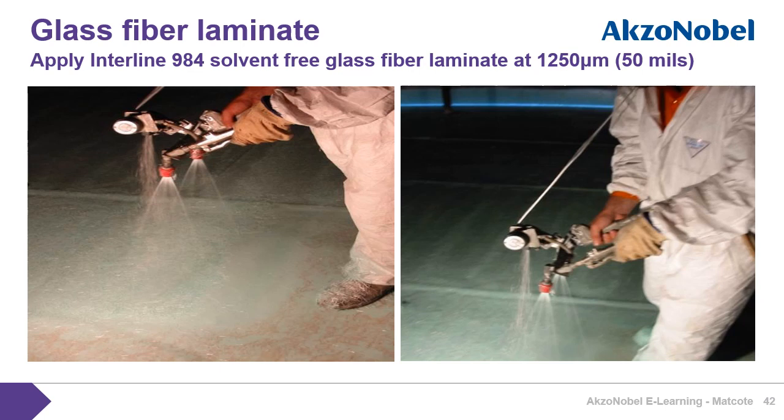These two photographs show the application equipment in use. As you can see, as the applicator walks backwards, he's laying down some resin first, then the chopped glass fibre, and then more resin.